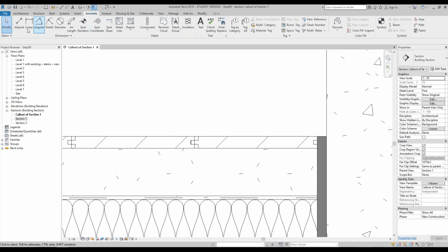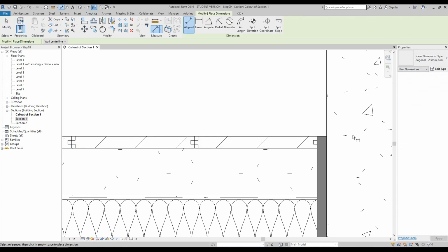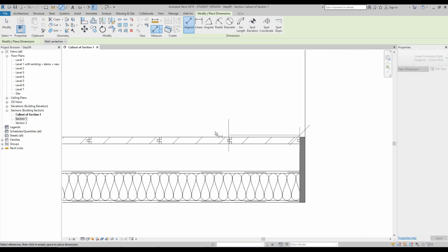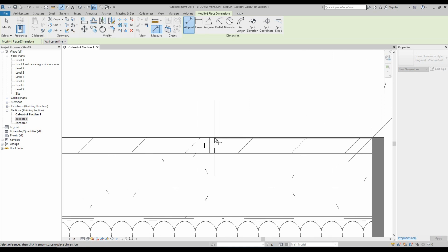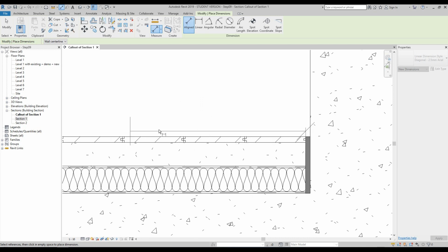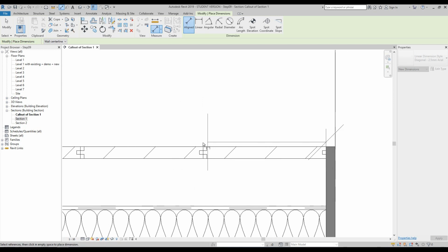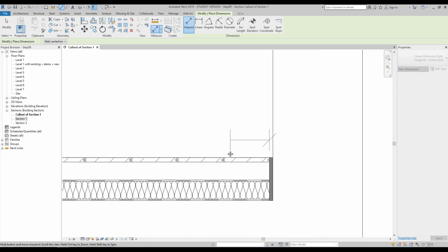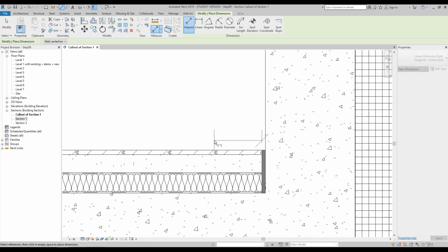Additionally, if I was to show you how to measure and annotate this, if I take this edge, you will notice that I'm not able to take a dimension from another edge because it's a repeating detail. You can see here nothing is highlighting for me to actually take an individual measurement. This is the bad thing about Revit, and again this just backs up the fact that you really shouldn't be doing this in a BIM model.